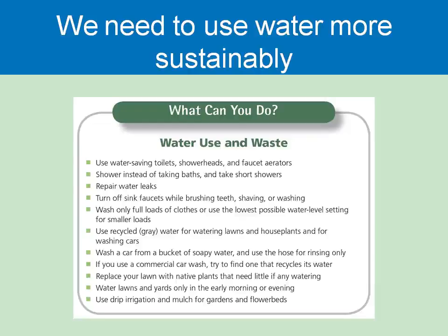In practice, this involves a porous membrane whose chemical nature is such that it has a preferential attraction for solvent while repulsion for the solute. Reverse osmosis has been commonly used to desalinate brackish waters and is also found to be a suitable, effective and economical method for the purification of water polluted by sewage effluents. Techniques introduced by CSIR for the control of water pollution have been successfully used for the removal and reuse of pollutants from industrial effluents.